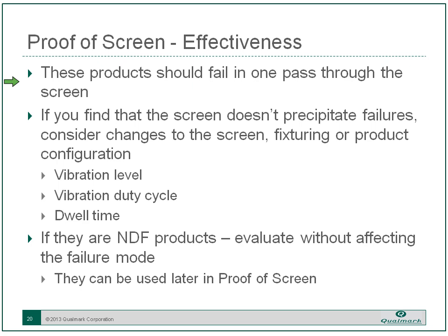If you need to reduce the stress of the screen, most likely you're going to need to be changing vibration, because that's the stress that really does the fatiguing. So look at maybe changing level or duty cycle on the vibration, or dwell time thermally.